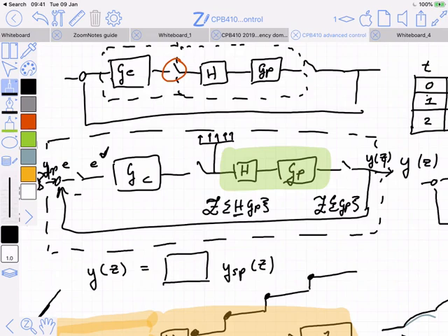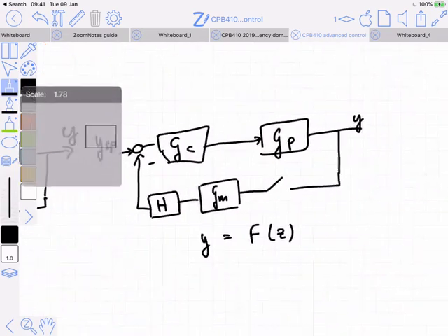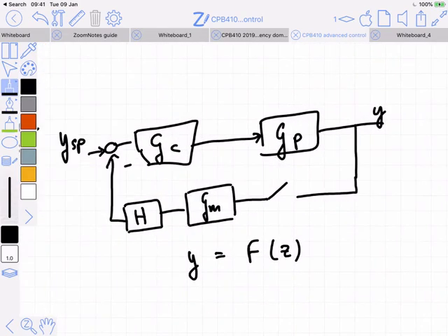It sounds very obvious because you've grown used to transfer functions existing, right? I introduced it, and you've used this transfer function idea, so it has become so obvious to you that obviously there will be a transfer function, and the transfer function will only be calculated once. It will be a function of the differential equations that define the system, and I can use that exact same transfer function for all the different inputs. This is not the case for discrete systems when one of the inputs into the system is not sampled, as in this block diagram over here.